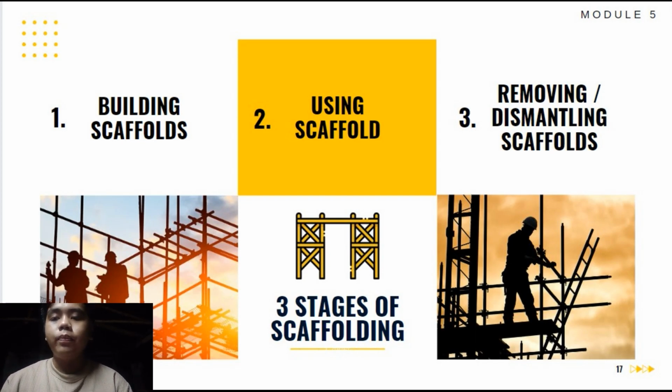Condition of fitting: might be distorted, stripped, missing, or bent. Condition of scaffold plank: cracks, spilled, damaged scaffold. Tag, set aside, repair or replace. Okay, for number 3 is erection of scaffold.